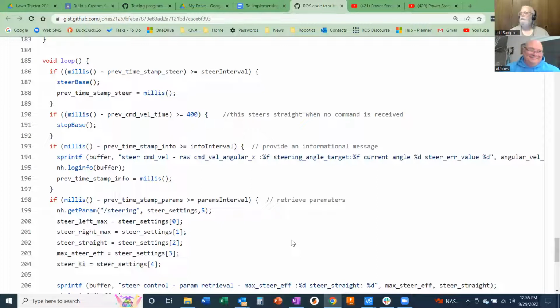With that, it's a little more complicated because it passes the packets at 12 megabits per second from your board up to your computer, but it also breaks it into packets. So it gets data into a buffer. When it decides it has enough, it sends off a packet. And if not, then it might just sit there a while. So I don't know how that's going to affect the timing, but it's something to play with and see what you can make that do.